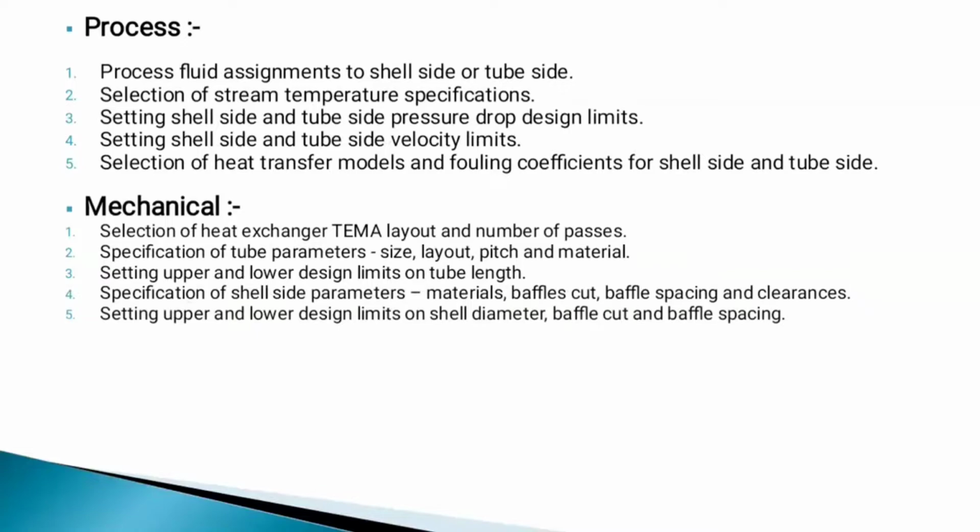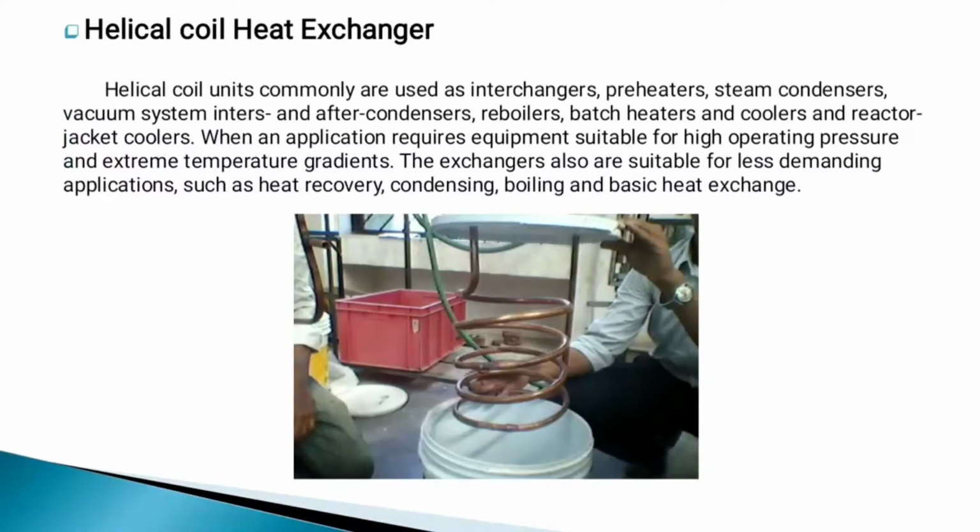The specification of shell side parameters: the material, baffle cut, baffle spacing and clearances. Setting upper and lower design limits on shell diameter, baffle cut and baffle spacing. The second point is the helical coil heat exchanger.